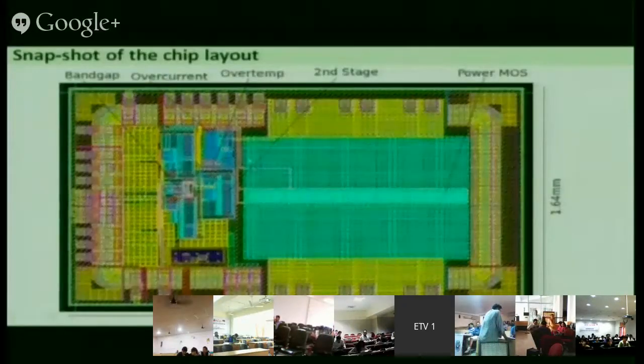These are the metal lines. This one is metal. This is a pad, and here this also is metal. There are 4 metals in this, so you are seeing only the top metals. Metal 4 and metal 3 are interconnected also. Here is the output stage, and 6 pads are used because there is more current. It has to draw a lot of current, which is why more pads are used. So this is a complete chip. Dimension is 1.6 millimeter by 2.4 millimeter.